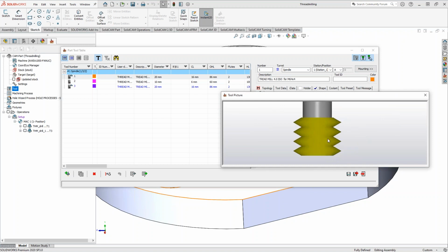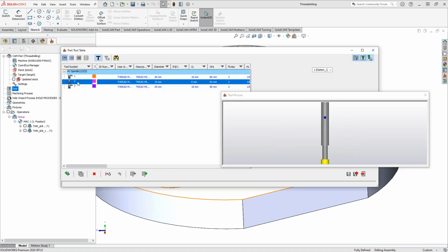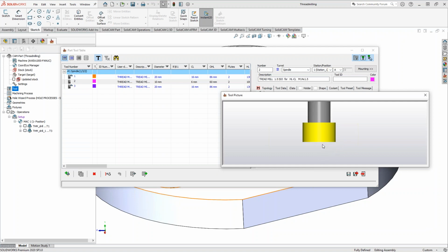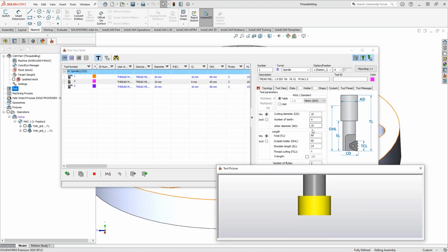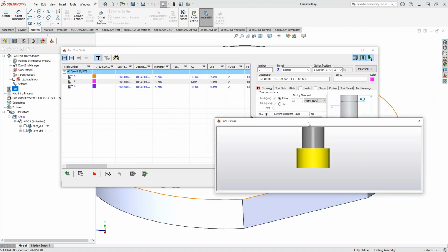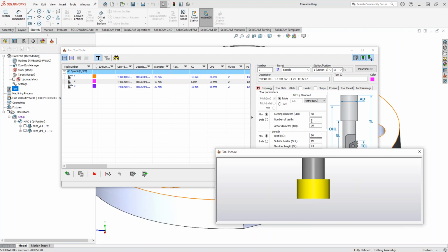Now, this is not required. You can generate a thread milling toolpath with just the default shape. The default shape actually looks just like that, and that's only because you're just defining a cutting surface, a cutting length. The number of teeth in use and all that are still defined. Your toolpath still comes out with the proper definitions, proper step downs, the proper thread. Remember I said before about the number of teeth. It'll still recognize how it should step down to generate all those threads.